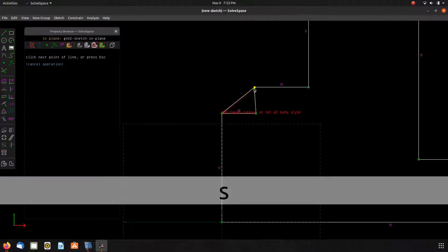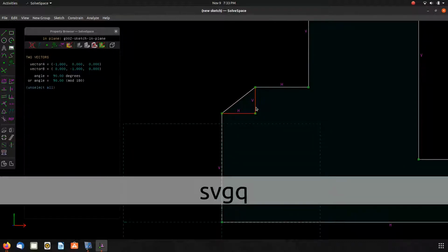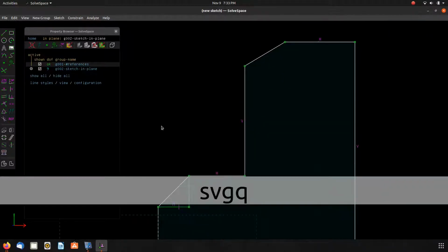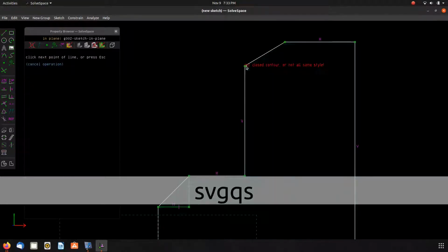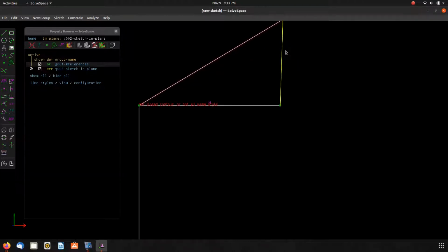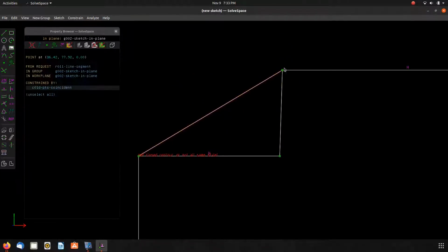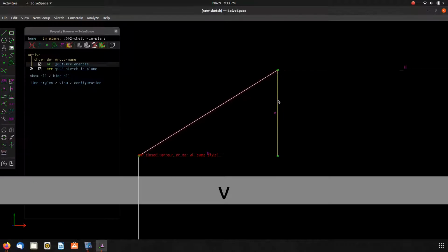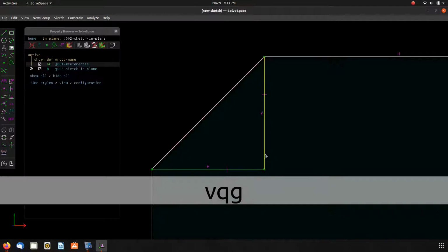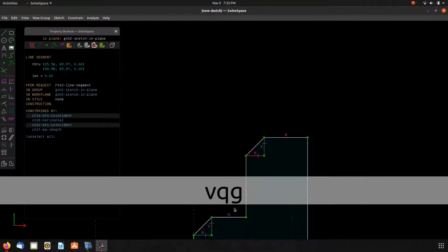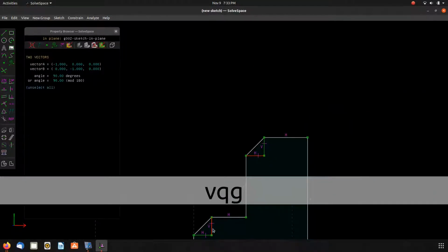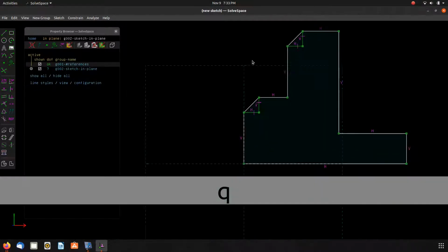Okay, here I'm going to build some intelligence into the model to define the chamfer by making those equal. That sets a 45-degree chamfer here and there. Also set a 45-degree chamfer by making that vertical. That and that, make those equal, and then make them construction lines. Then we'll tie the two chamfers together since they're the same by pressing Q.